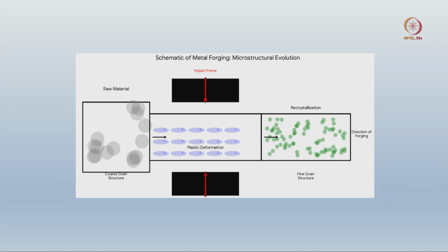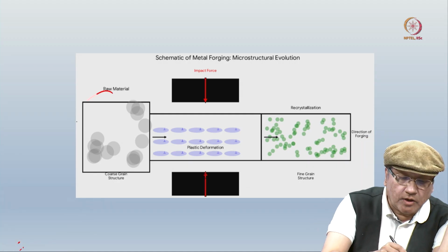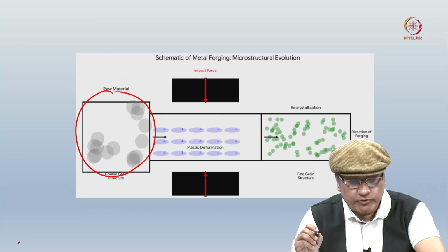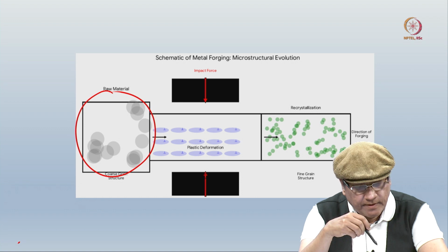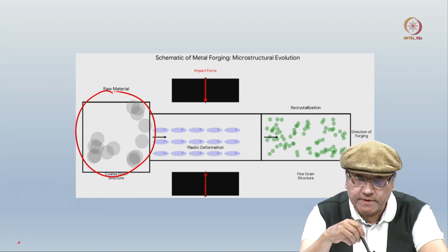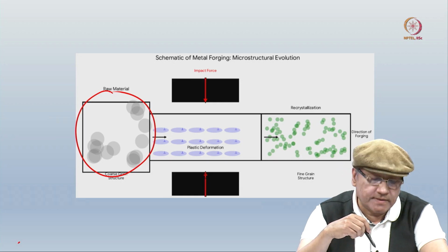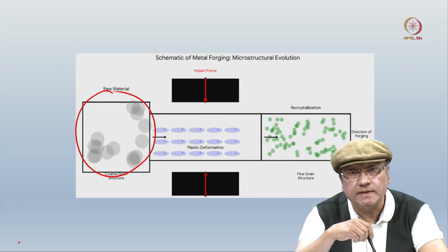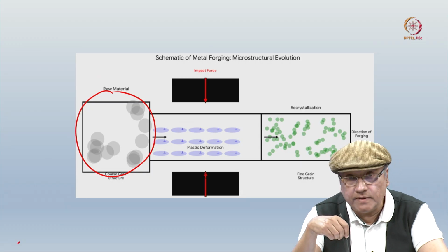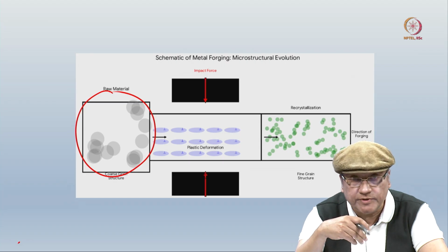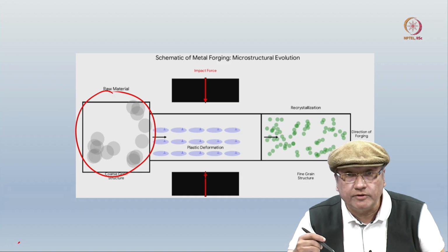This is an example of forging, in which you have here on the left this component, and essentially what you do, you make this component undergo huge impact, enormous force which shrinks the width of this component, and you see in the process the component loses its elasticity and undergoes large plastic deformations, and in the process you have lots of different phenomena, these dislocations which are part of this defect microstructure that evolves, and you have recrystallization, a finer grain structure.